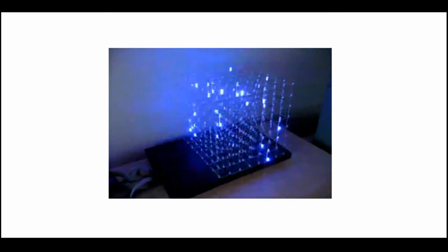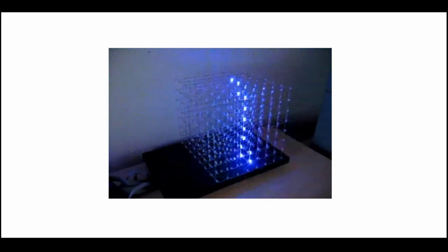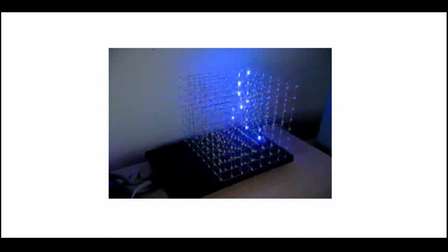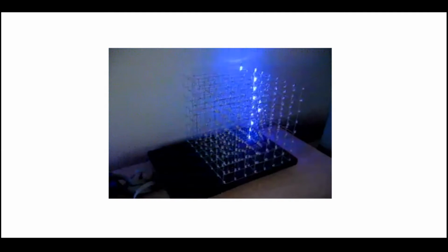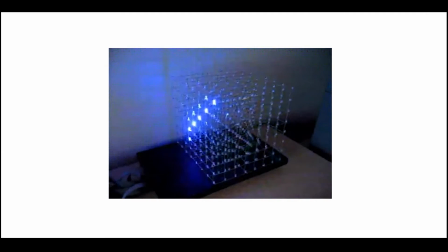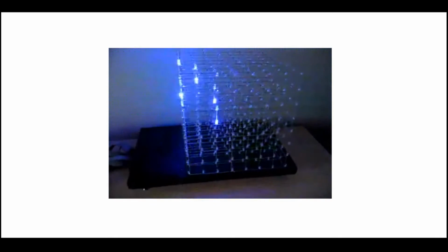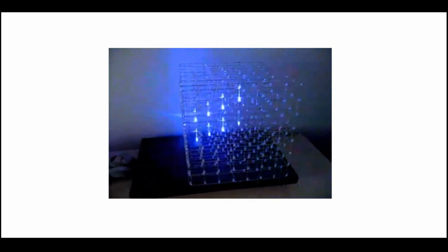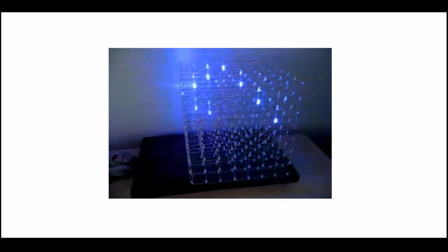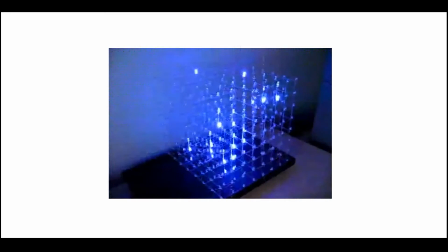You can do one layer after another and cycle through. If you do it really fast, you can beat the minimum number of frames per second that the eye can perceive, and exploit that to create an illumination where the LEDs across the layers appear lit up at the same point of time. So that's the key idea behind solving the first problem.